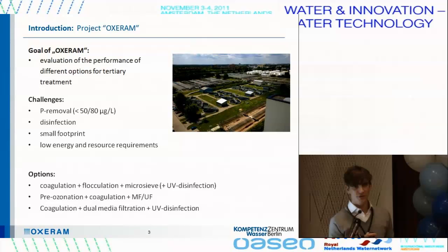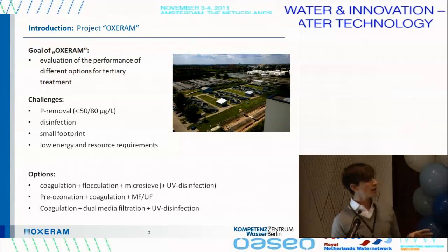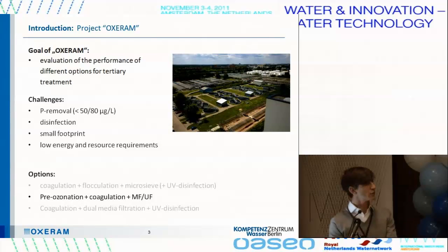The tested options are different combinations of processes. The first is coagulation, flocculation, and microsieving, versus the process of pre-ozonation, coagulation, and low-pressure membrane filtration, versus coagulation and dual media filtration. And in my study, I focused on this process.